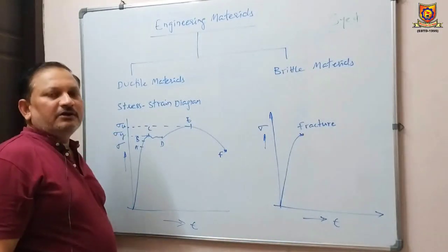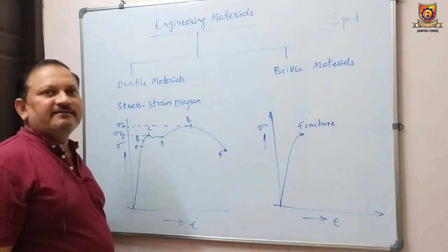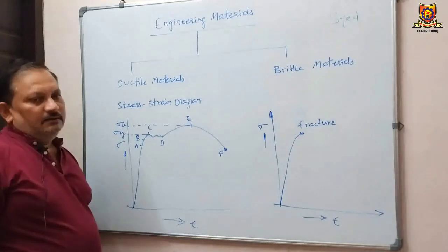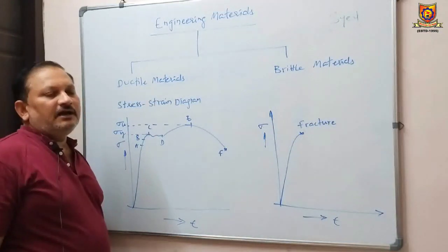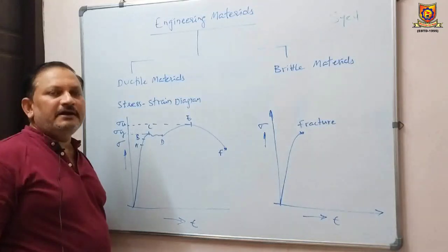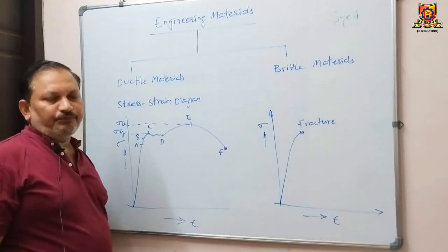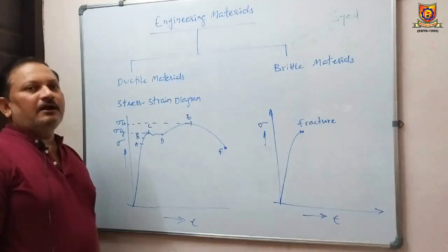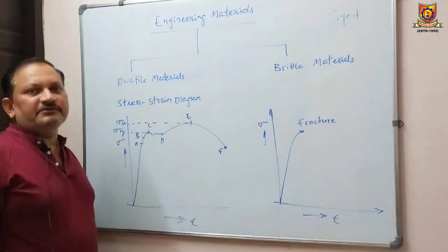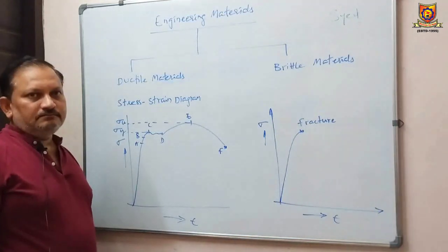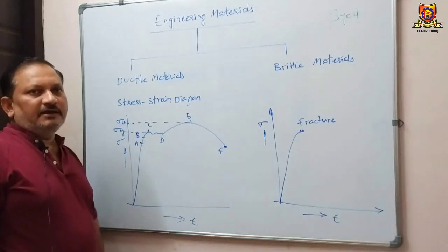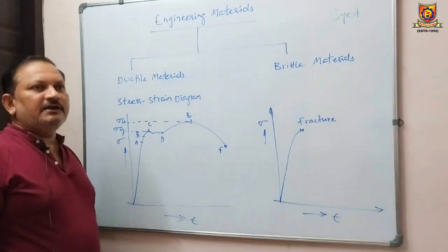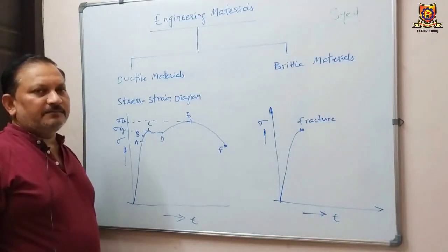Today, I am going to give a lecture on design of machine parts against static loads. As we all know, the majority of our machine parts are made with ductile materials. Why? Because ductile materials undergo some kind of visible deformation before their failure. They give a kind of warning before failure, so that a design engineer can take some corrective action and replace the damaged part.